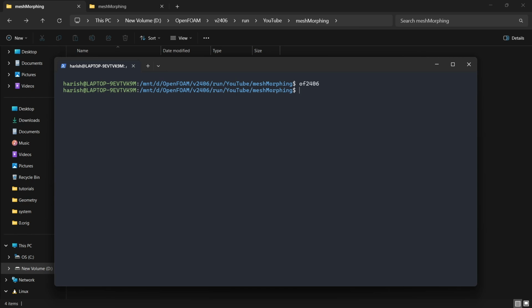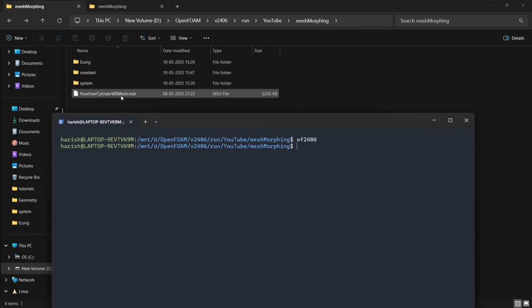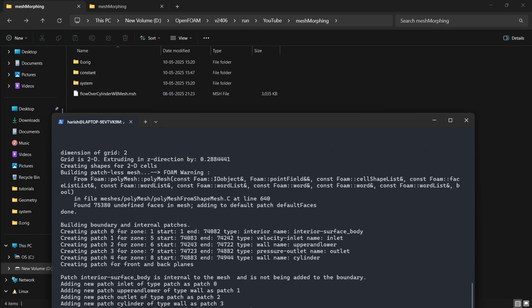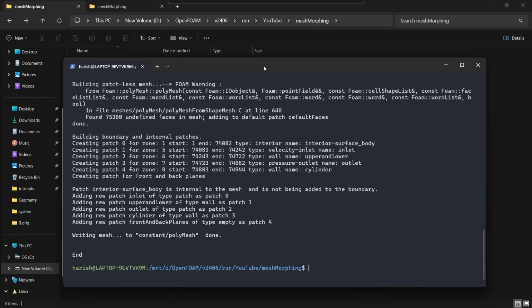Okay, now we are jumping into the tutorial, and this is common for all. If you decide to use the mesh which I give you, which comes with this case, then all you have to do is import the Fluent mesh, which is fluentMeshToFoam, followed by the file name. So you just have to type this and the file name, which is in .msh, press enter, and we will be getting the mesh.